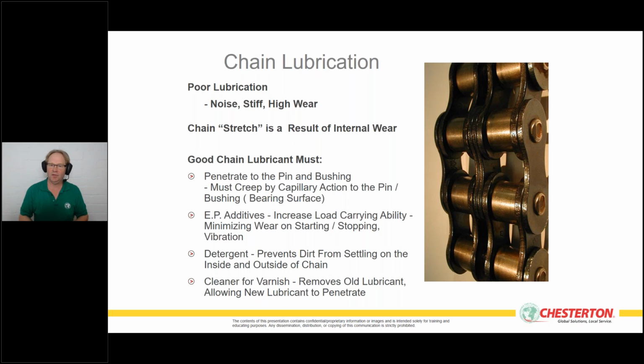So what is the reason? I'd like to give you an idea what the main reason is and what a good chain lubricant needs to do to overcome this. There are 4 major points you have to remember. First of all, an oil needs to be able to penetrate. If you apply an oil onto the chain, and the oil stays on the surface of the chain, it doesn't lubricate where it should lubricate. It should penetrate into the pin and the bushes of the chain. So it has to go through this fine tolerance to get actually into the chain.